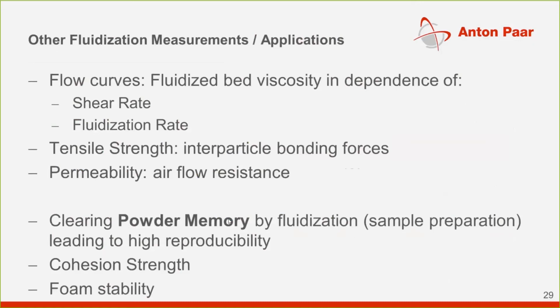The applications we are interested in also include, for example, clearing the powder memory by fluidization as a sample preparation mode, which can lead to high reproducibility for a lot of different measurements, like, for example, the cohesion strength. So in the cohesion strength, the powder is first fully fluidized before the measurement is carried out, in order to remove intrinsic influences by the powder, by the operator, by the filling, and so on.